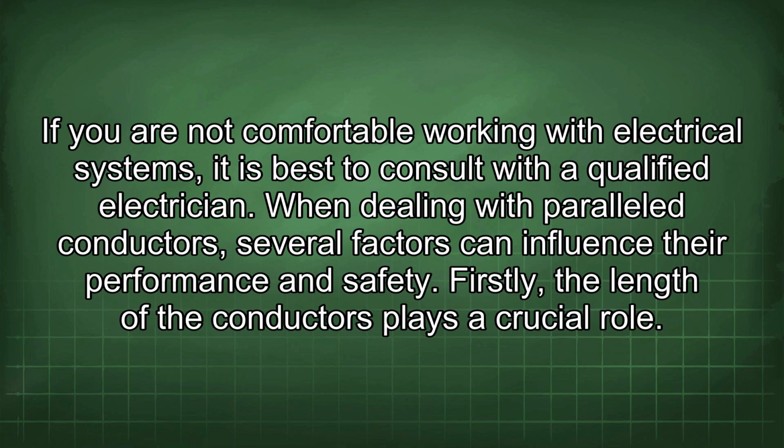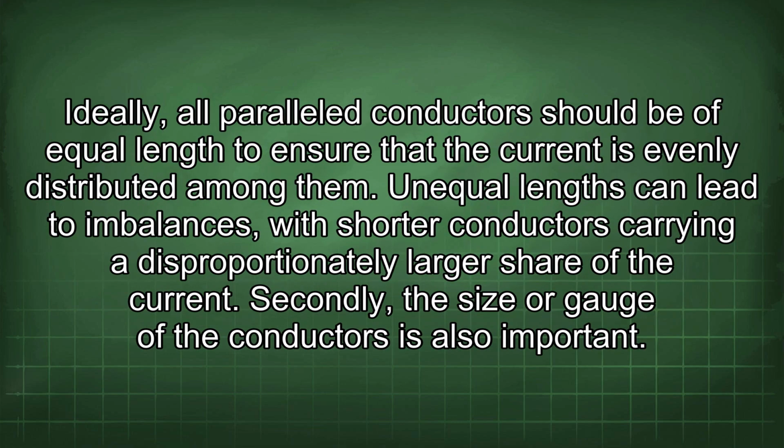qualified electrician. When dealing with parallel conductors, several factors can influence their performance and safety. Firstly, the length of the conductors plays a crucial role. Ideally, all parallel conductors should be of equal length to ensure that the current is evenly distributed among them. Unequal lengths can lead to imbalances, with shorter conductors carrying a disproportionately larger share of the current.